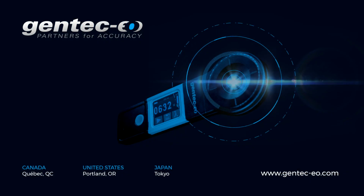Alright, we hope you enjoyed this workshop and that you feel confident how to remove background noise for accurate laser beam profiling and power measurement. Stray light does affect your beam diameter and laser power measurements by making them larger and higher by error. We also explain how to remove thermal offset with thermopile detectors, so let's be precise together and contact us.